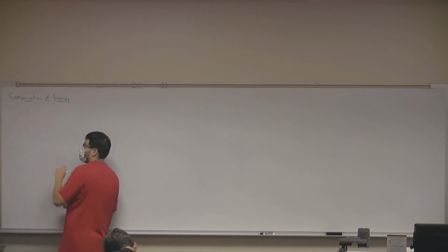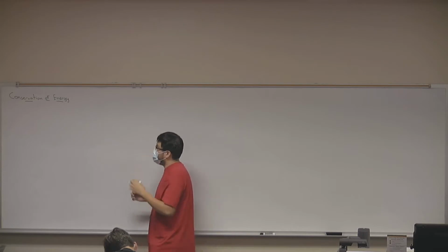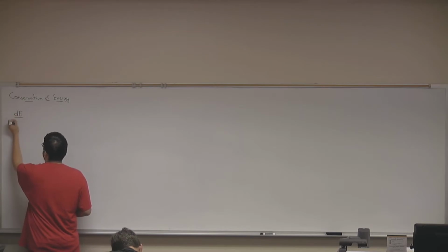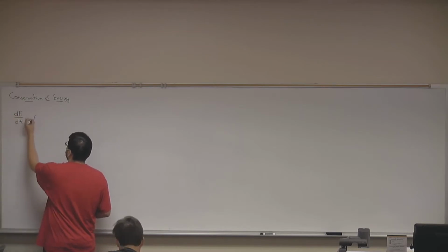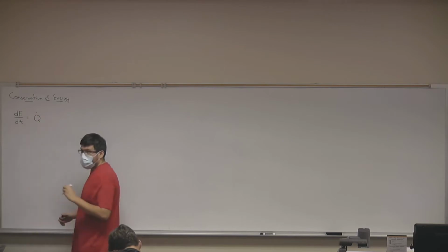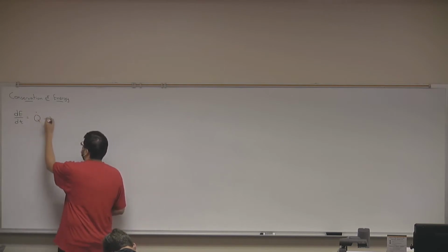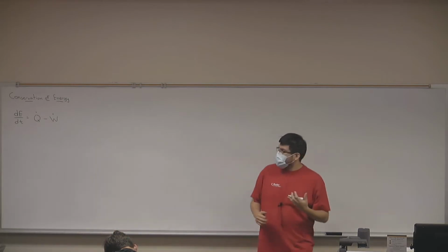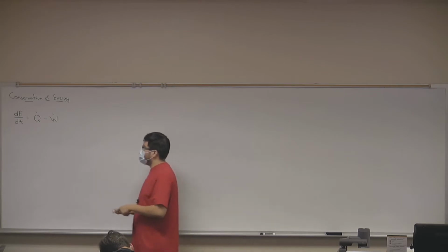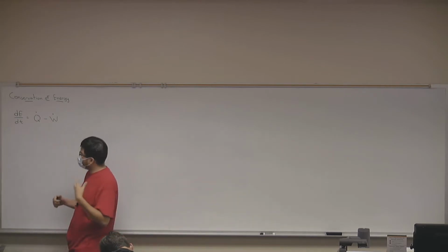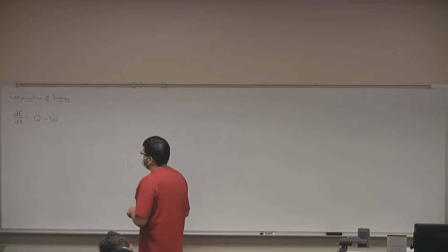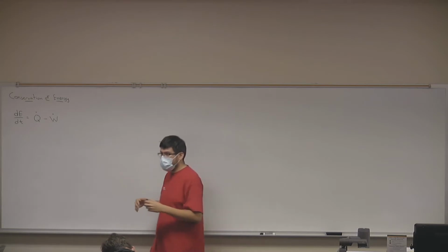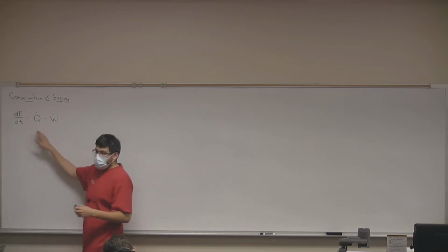So if you're taking thermodynamics, or if you are planning on taking thermodynamics, you will learn that the first law of thermodynamics tells us that the rate of change of energy with respect to time in a system will be equal to the rate at which heat is transferred, okay? And the rate at which work is done, okay? Whether it's a positive or negative sign really depends on your sign convention, and different fields use different sign conventions. So for this particular class, I'm going to set my work rate to be negative if it's done into the system, right? And my heat transfer will be positive if it is transferred to the system.